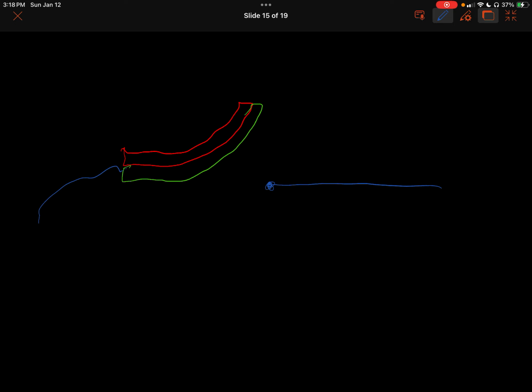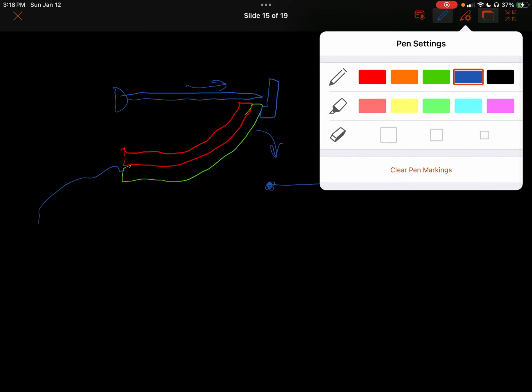Now, if this was the case, it would just bend like that, and we would lose our contact. But as soon as it disconnected, it would start to cool down. We don't want it to go back into place. So there's always a little hook right here that's going to keep it from going back down. And that's the part of the circuit breaker that comes up, it pops, and our circuit breaker sticks out. To reset it, we push our circuit breaker plunger back in. If we push it to the right, that'll allow this bimetallic strip to drop back down once it's cooled and reconnect the circuit if we need to. So that's a thermal circuit breaker.